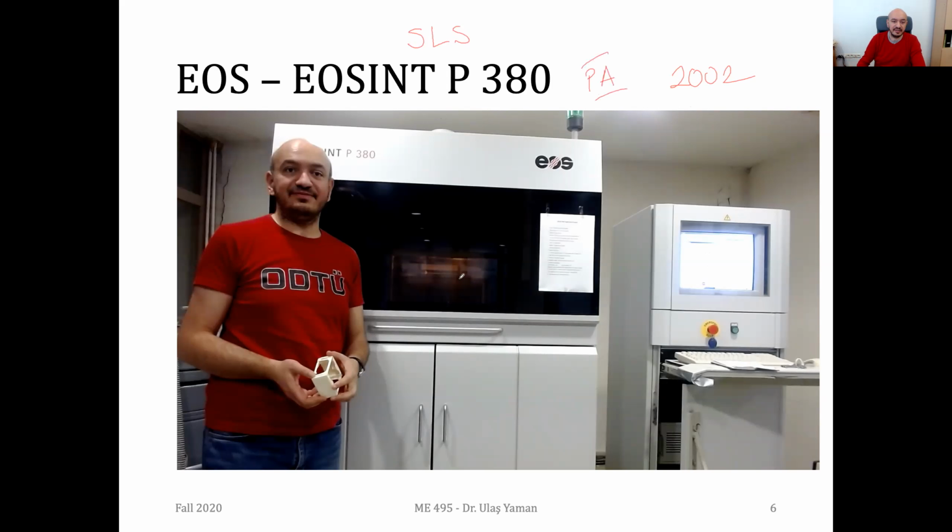You'll see in a moment that this has a build chamber, which is going down, but the powder chambers are on the left and on the right hand side. This time, the powders are poured from top to bottom, not from the chambers below. This is a reverse configuration, but other fundamentals are the same. Another thing, this video is already available on the YouTube playlist, so you can look at it afterwards.